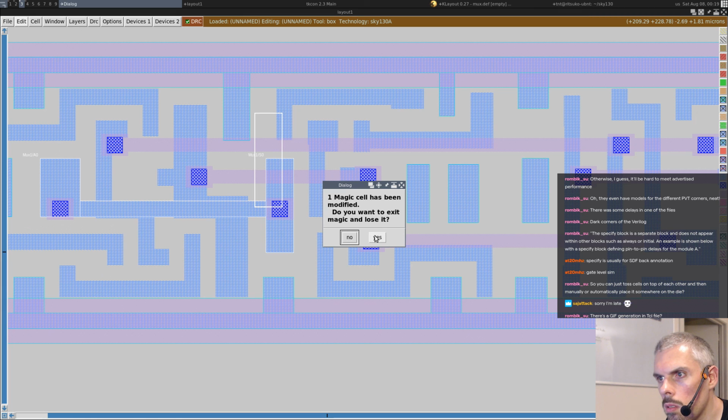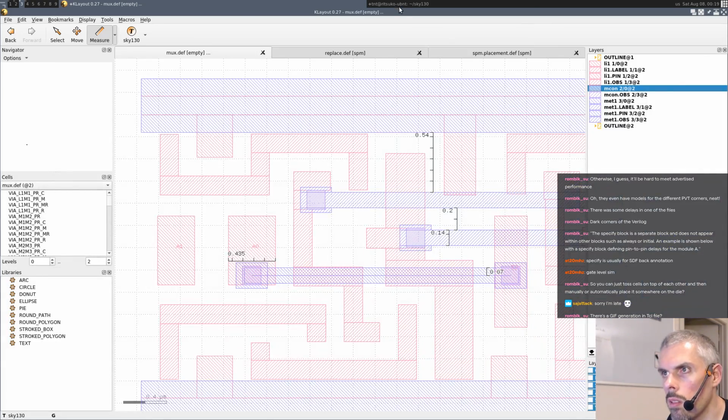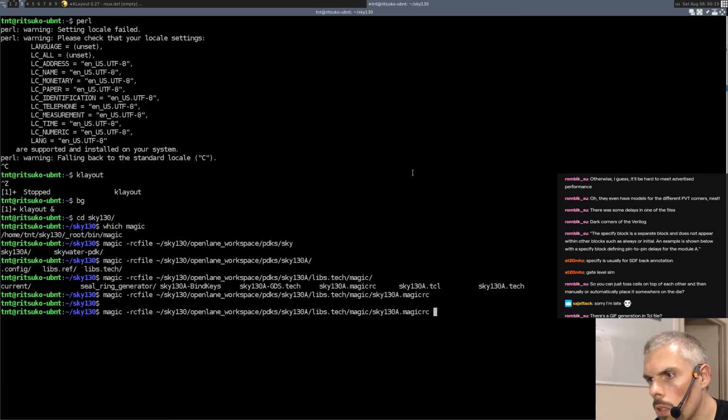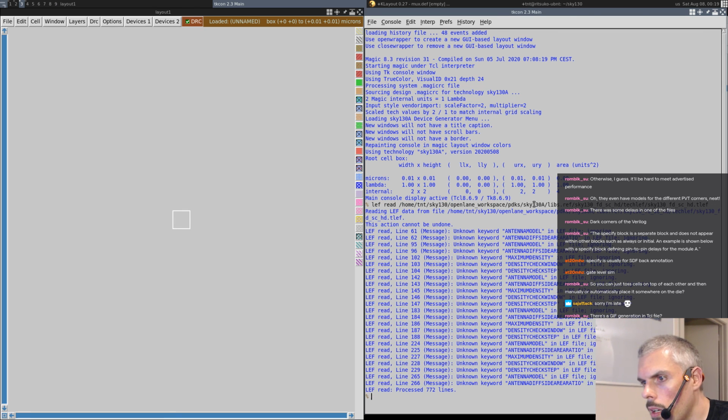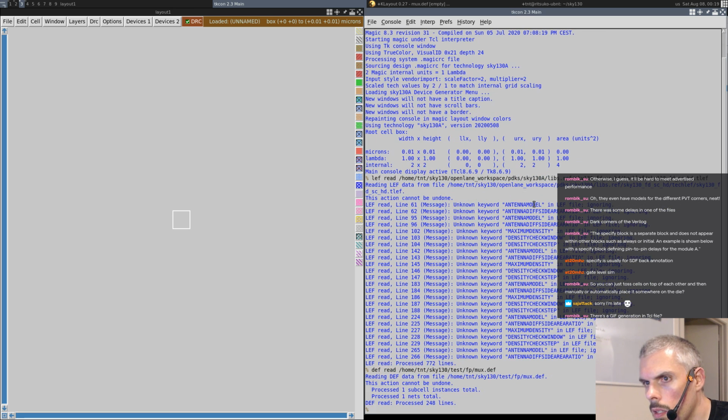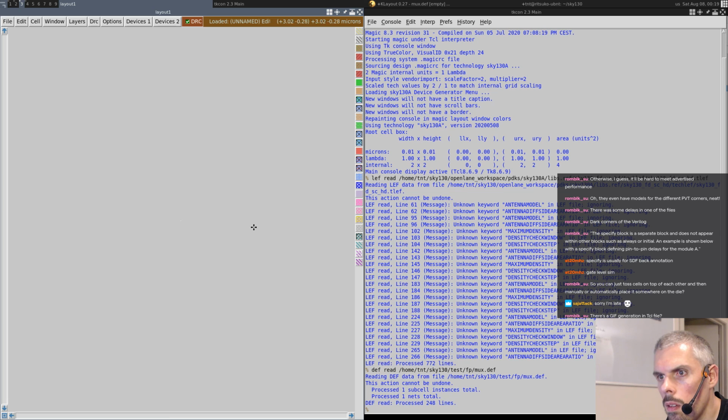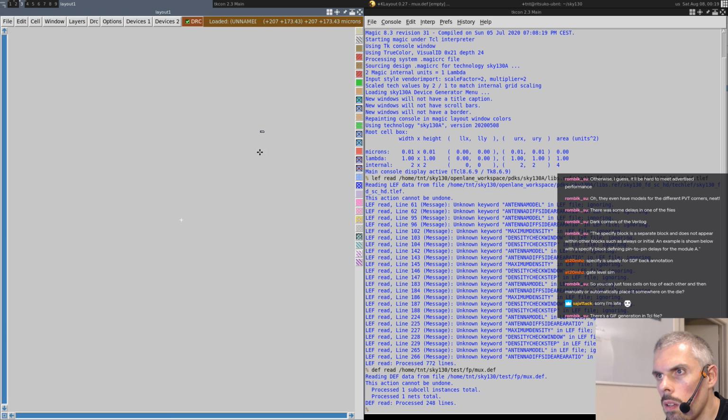Let me restart it. Do you want to exit Magic and lose it? Yes. Let me restart Magic. Read the technology file. Load the cell. Find the cell.